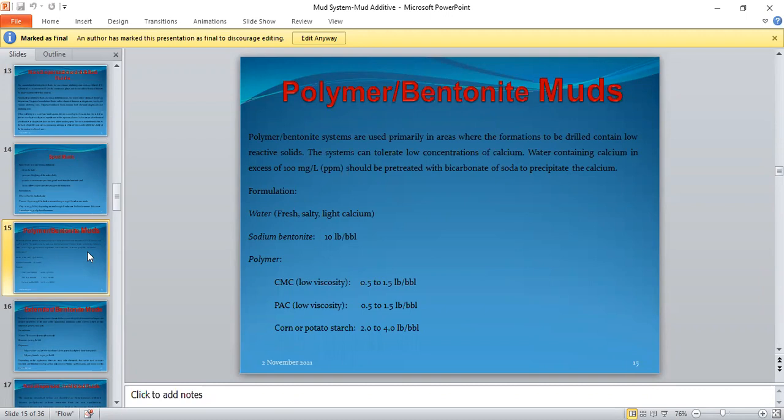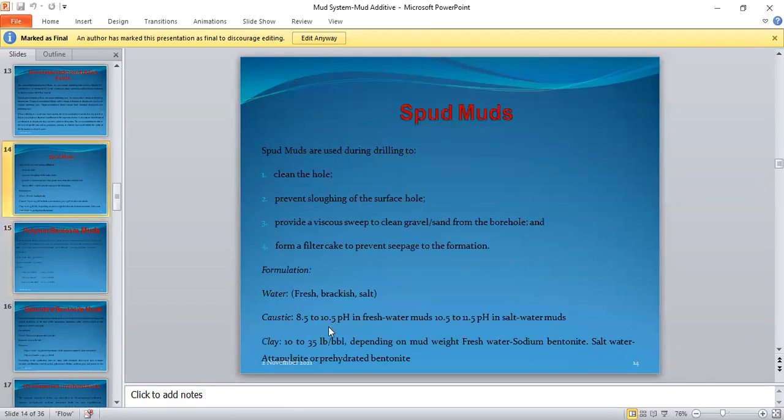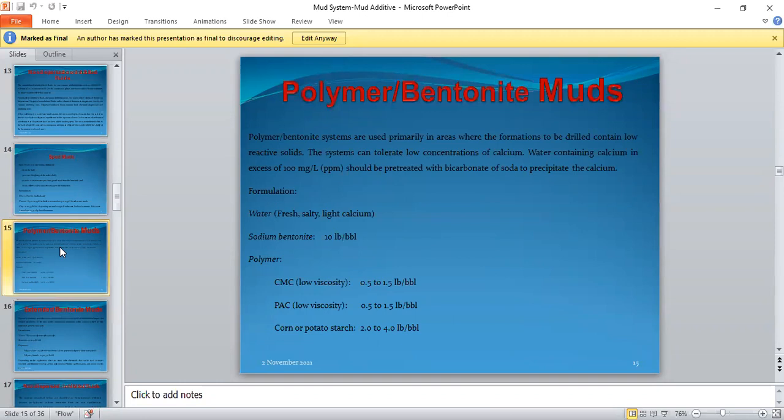Now I want us to take note. If you watch here, the bentonite concentration, that's the clay, sodium bentonite, is 10 pounds per barrel. Look at in the case of spud mud, 10 to 35 pounds per barrel. Bentonite gives you viscosity. Polymers also give you viscosity. So in this case, we want to reduce the bentonite.